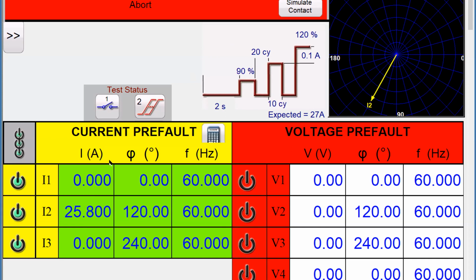And again, you're seeing here, see how the increment in the pulse? As I look at 3, this will be my C phase. You'll notice that this is actually pulsing. So it looks like it's ramping and incrementing up the value, but actually what it's doing is pulsing it on for your 10 cycle delay on and 20 cycles off. So each one is actually working.